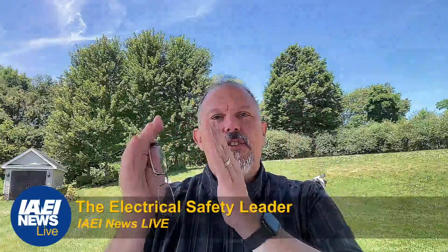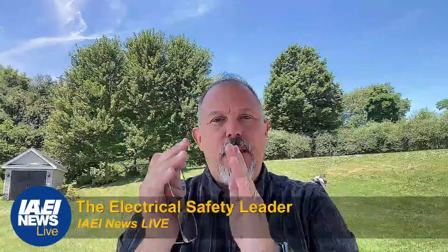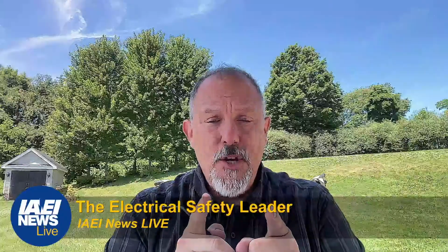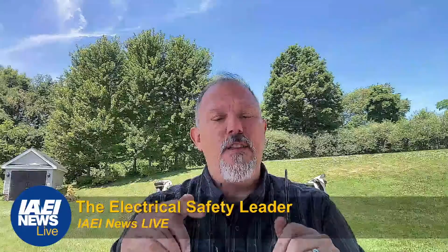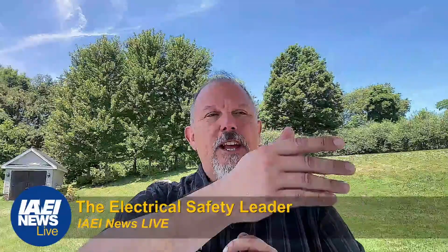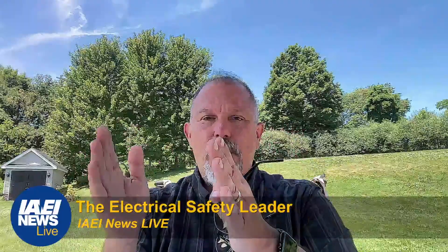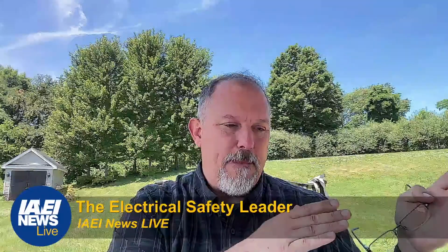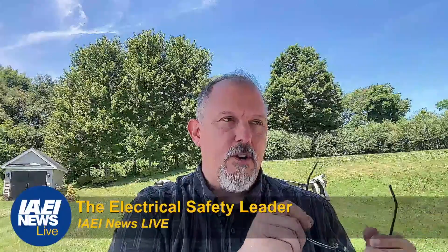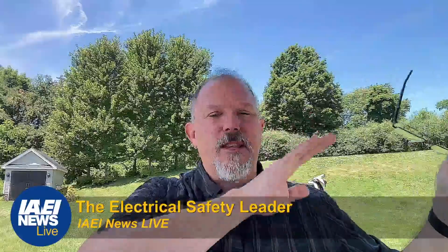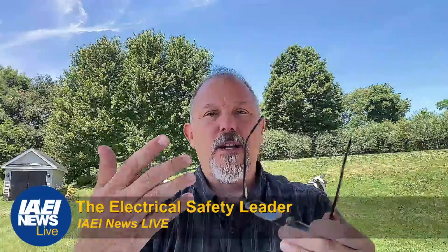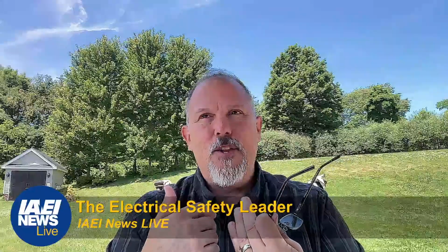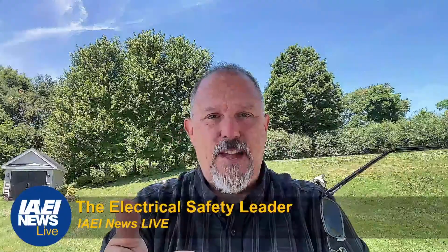What you're saying is your policy says you can't open a box energized. Yet, you have to assume it is energized until you verify absence of voltage. So even if you go through lockout tagout procedures, you're going to go back to the overcurrent protection, come back to the switch or the circuit breaker, and lock and tag it out, and then go over to the box and open it. But when you open it, you need to then verify absence of voltage.